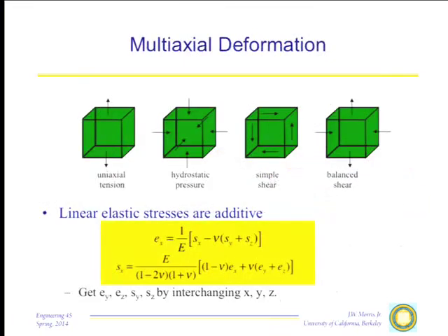There are actually 4 kinds of stresses that we have to be concerned about that are applicable to materials. The 4 common stress states are the following basic stress states. Uniaxial tension is with my tensile bar. I just pull in one direction on the bar, get its response. Hydrostatic pressure: suppose I take a cube, I just put it in water or put it in the atmosphere. The pressure will impose an equal load on all of its surfaces. So hydrostatic pressure or hydrostatic compression is a situation in which I have the same stress in all 3 perpendicular directions. Simple shear